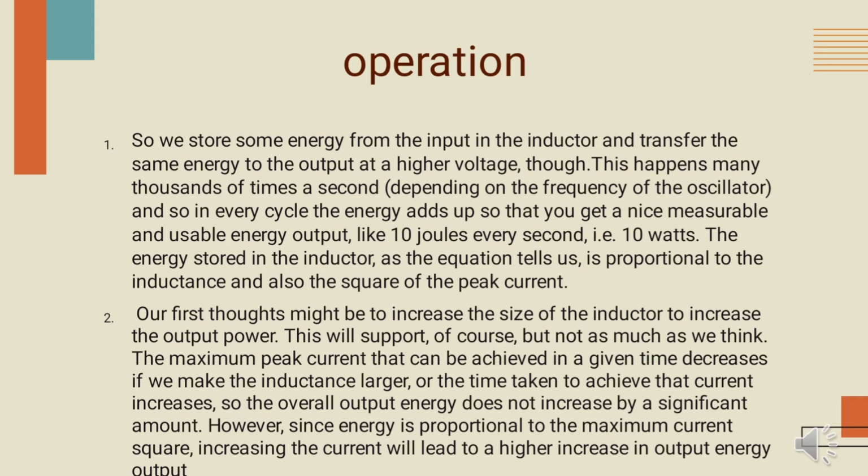The second one is the MOSFET itself. During step 3, the MOSFET sees a voltage that is the supply voltage plus the inductor voltage, which means the MOSFET has to be rated for a high voltage, which again implies a rather high on resistance. Boost converter design is always a compromise between MOSFET breakdown voltage and on resistance.